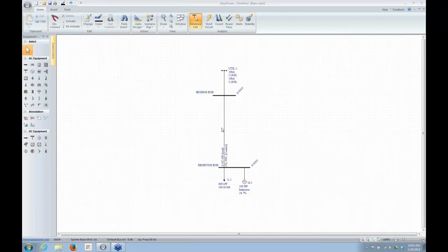The typical solution method involves iteration to narrow down, kind of zoom in on the right solution. In power flow, we're trying to match all the power in with the power out, and all the losses, all the kW and all the kVARs need to balance out. So that's the basic power flow solution we're trying to look at.